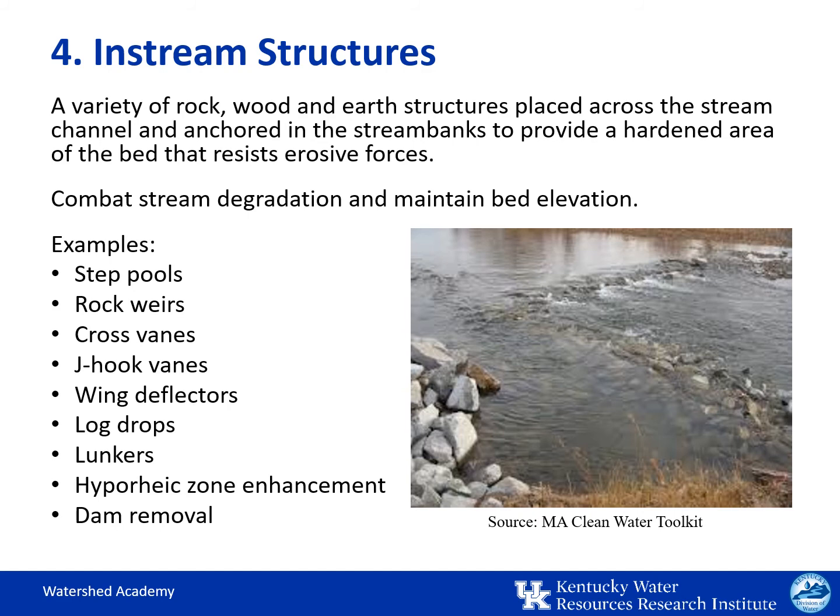We'll look at a number of examples of these controls, but in general, they're designed as a U or V shaped to create downstream scour pools for fish habitat or resting. If properly applied, these structures can be very effective. Sometimes, however, their effectiveness can be lessened by unforeseen changes in the channel, as the stream might meander around the structures, or they can be destroyed by excessive flows or even catch too much gravel. Log structures will also eventually decompose. And therefore, some designers will just try to stabilize the floodplain and allow for flexibility in the formation of the channel over time.